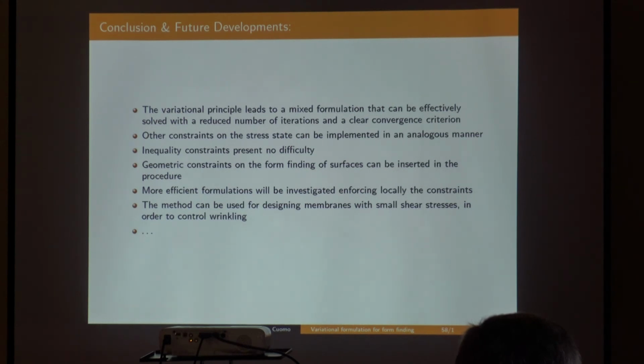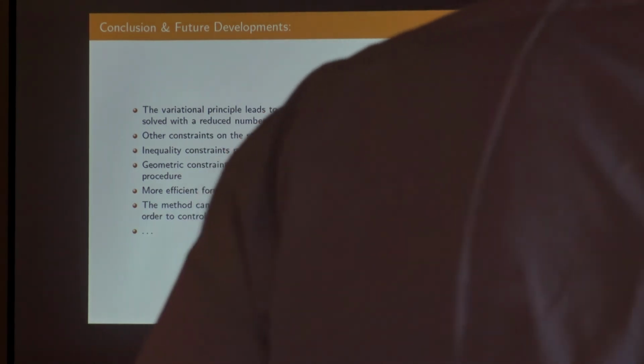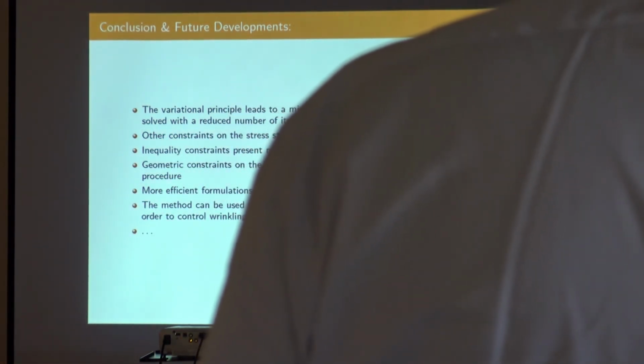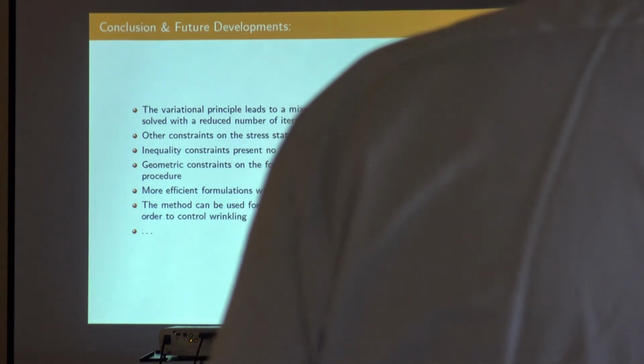How are you dealing with that problem? Yes, but what do you mean, the constraint? What constraints? I mean, you have this in the catenary, you have the inextensibility. Yeah, that's the case I've shown. I enforce the length of the catenary. Yes, but in the case you have an extensible catenary, you have two configurations: the equilibrium final configuration, and the real reference configuration, because it is unloaded. You have to make two variations. And the configuration is with another length.